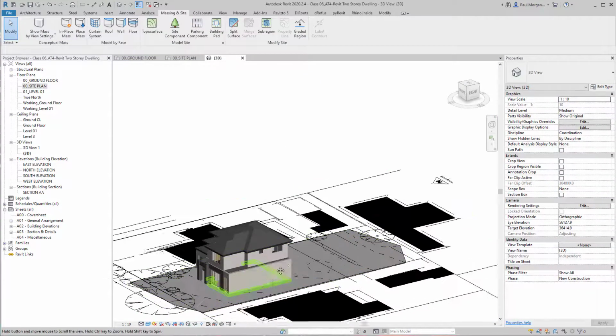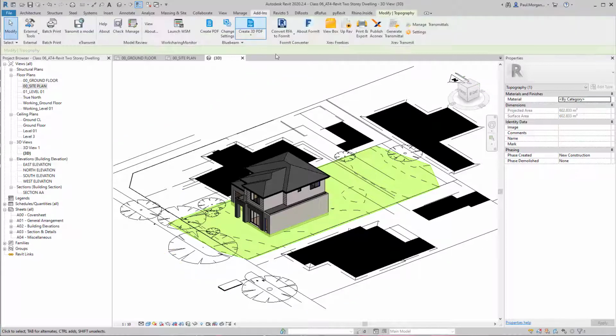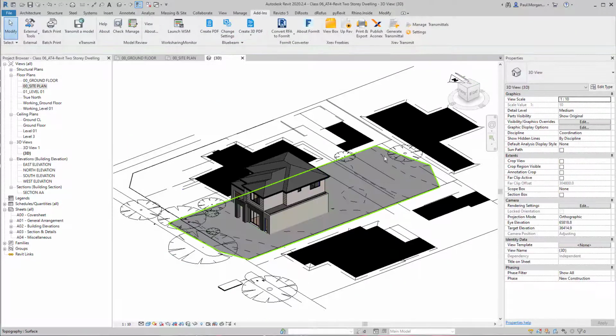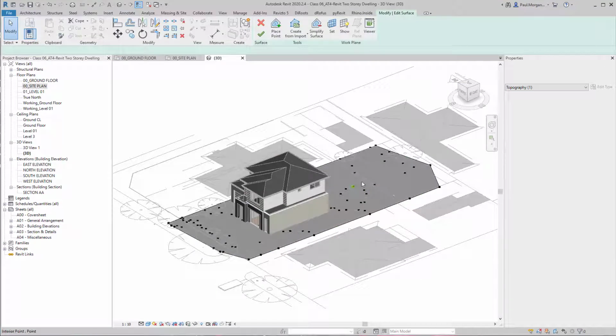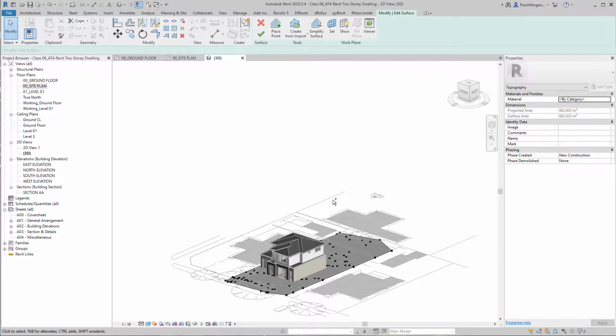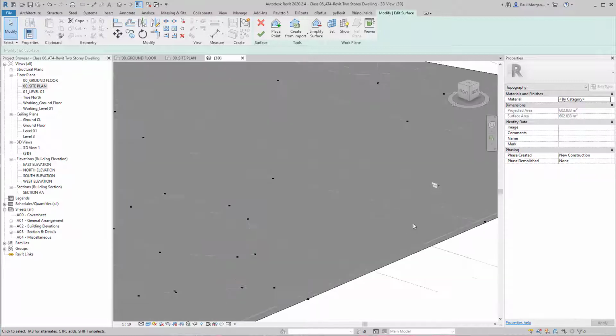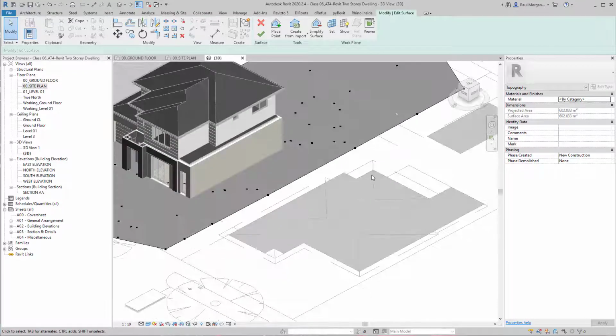But what I am going to do is a bit of a hybrid. We've already got the points that have been created for us. I'll go Edit Surface. All the points are already created. I just need to now reference those points, select them, and give them the right height reference. Now, this is going to look weird because it's going to end up miles above our project, because the levels that we created for our project were incorrect, and we need to move our levels after we're done.